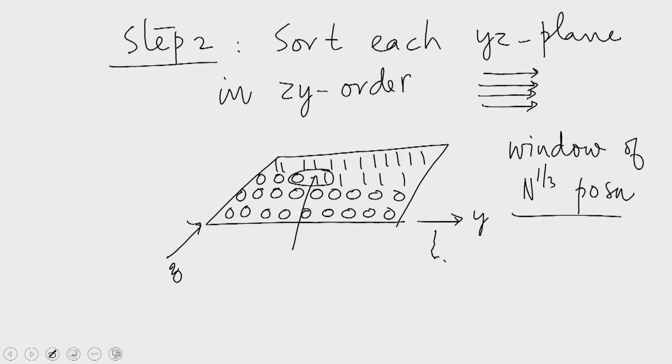If I take the first y line from here, the first y line from the next zy plane and so on, and aggregate all of them, I will get the first xy plane. Now, here I find that this plane has exactly one dirty row, a dirty y line. When I go to another yz plane, the dirty y row there could be either the same one or the adjacent one. It cannot be any other. Therefore, there could be at most two dirty xy planes in the entire mesh.